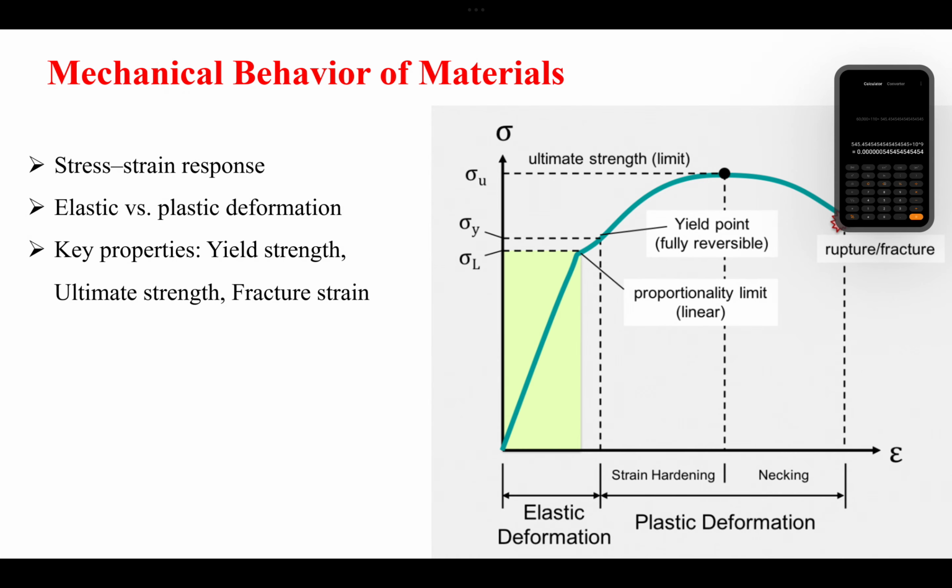Okay, so mechanical behavior very briefly. When you have a material, we did talk about the elastic deformation, that it deforms linearly in this region, so you will have a straight line in this region. Okay, and that is why we call it the elastic deformation, because in this case the stress is proportional to the strain, so it is elastic. Now in this region the body should be able to return to its original position.